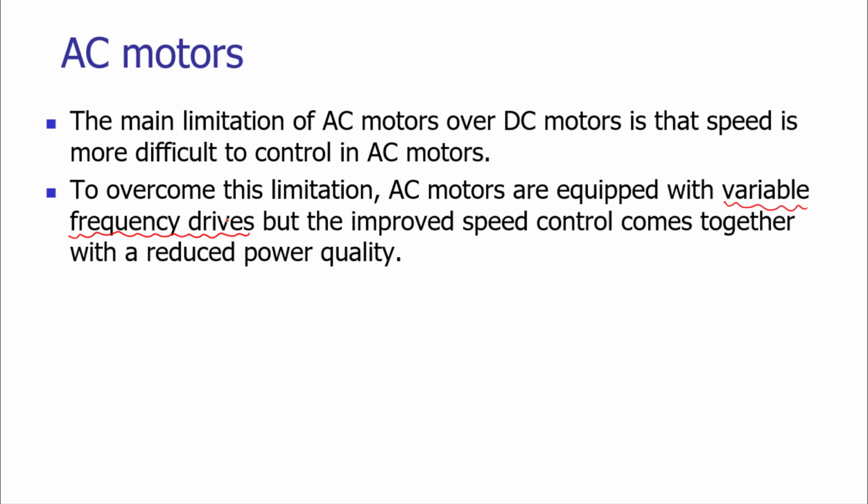So by using these variable frequency drives, there is improvement in the speed control, but the power quality would be reduced. In the transition from the low level to the high level through the variable frequency drive, we may reduce the power magnitude. We may not have the intended power to be applied at the load.